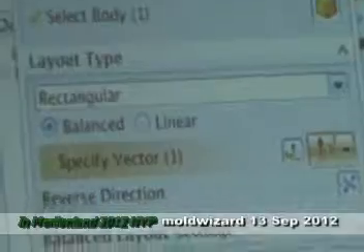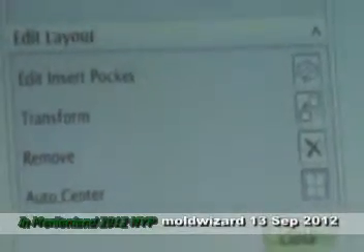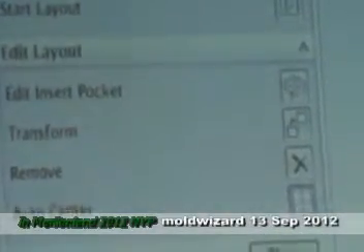So the last step under this page will be auto center. Auto center, because this 0 point will be the 0 point for the mold base, the 0 point for the whole mold line. So we try to locate everything according to the 0 point. So now we close it. By doing this, I think now we are able to decide the mold base size.